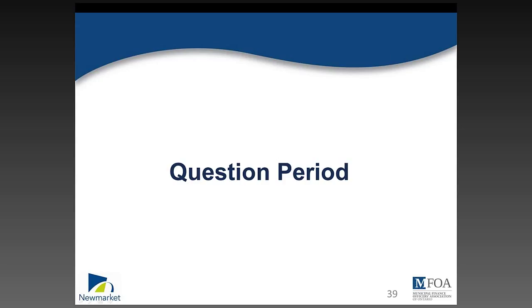Awesome, thank you. Next question is, how do you do your random testing of water meters? So the random testing, you select them at random. You don't choose based on any characteristics. Don't just pick the old ones. Don't pick and choose. Just select them randomly. And then what you do is you take the meter and you test it through 3 different flow volumes, one low, one medium, and one high. And then you see how they perform at each level, because there are things that can go wrong at different levels.